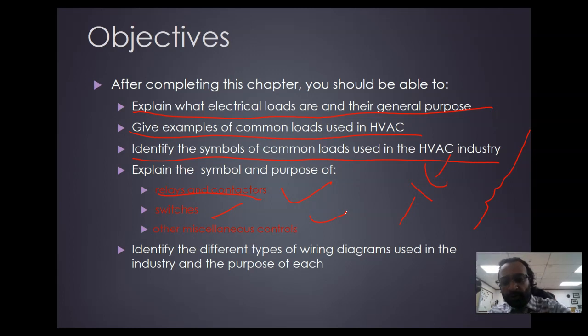Okay. Also, we'll talk about wiring diagrams. What are the types of wiring diagrams? There are some wiring diagrams that are very involved and have too much information. Those are called factual diagrams. They have every little thing on the diagram. And again, you can always request another, simpler diagram. There's an installation diagram, which basically just tells you where wires go in and out of the control, and the factual diagram has all the components and the wires inside of the control or the equipment.